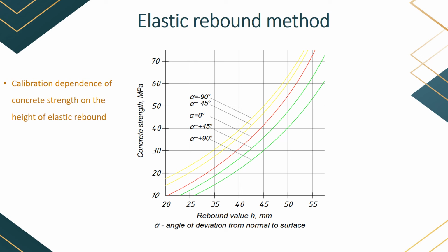The essence of the third impact action method, plastic deformation, consists in constructing a relationship between the size of the deformation imprint on the sample and its strength. With the help of a device, a spherical striker hits the material of a structure, as a result of which a deformation area is formed in the testing plane.